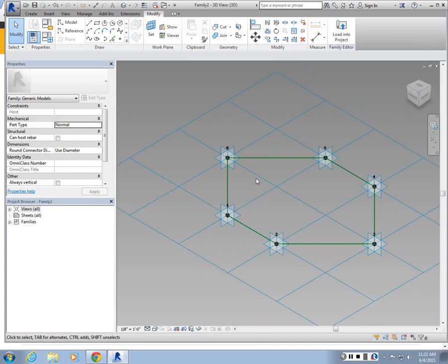If I'm modeling this in the parametric modeling environment, and I'm parameterizing how this tile works, like the profile of it, extrusion of it, values that are happening on it, there could be a dimension here, another dimension here, angle here, profile thickness, all of those. You would basically export an Excel sheet with all those numeric values, right? So what the fabricator gets is they know they're doing a hexagonal tile, and there are edge values, as well as angle values, as well as thickness values.